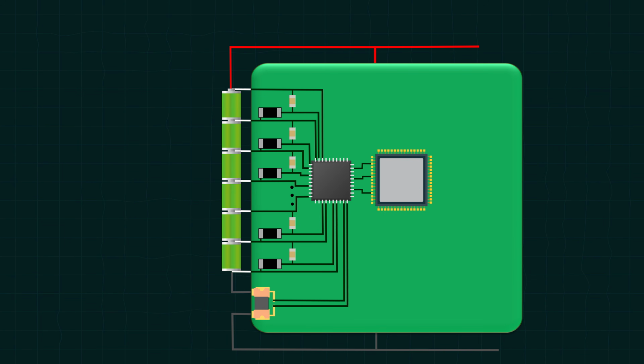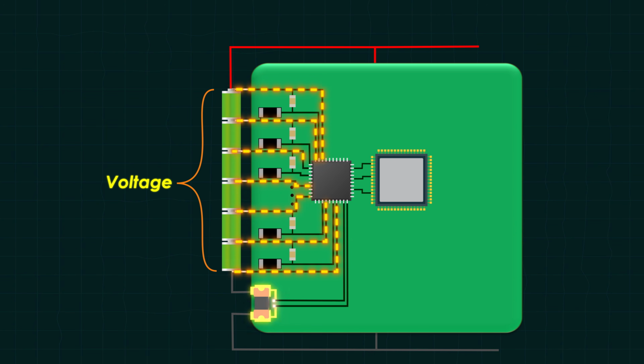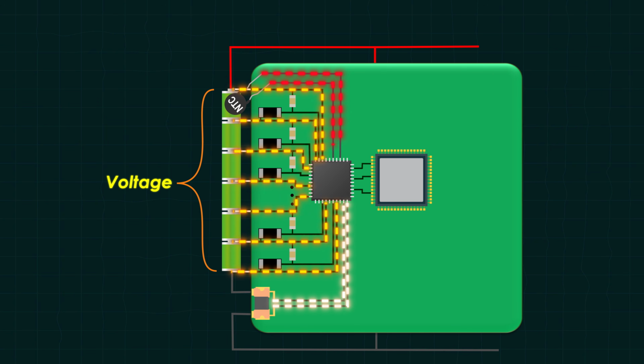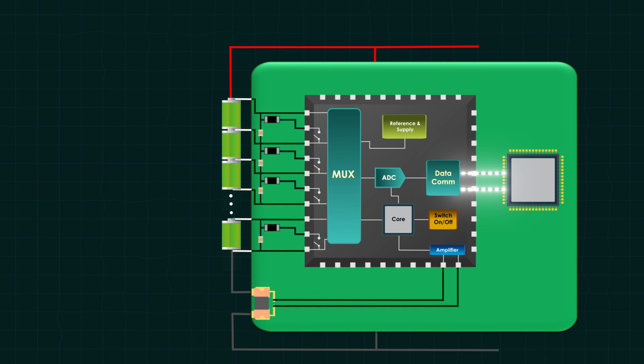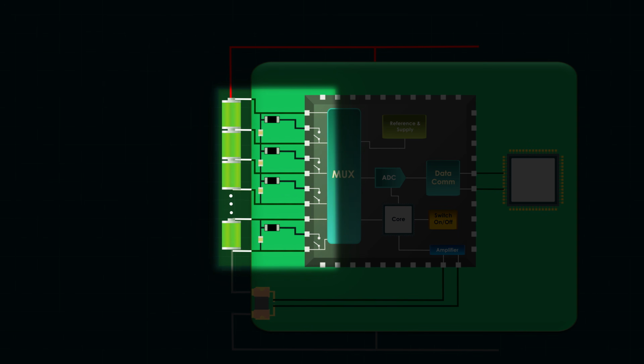In other words, it's an electronic circuit, often a dedicated chip, that sits right next to our battery cells and measures everything important: cell voltages, pack current, temperatures, you name it. The AFE takes all these tiny analog signals and amplifies, filters, and converts them into digital data that the BMS's brain can understand. It's a special monitoring chip with multiple channels that watch over the battery's health, kind of like having a mini multimeter on every cell.